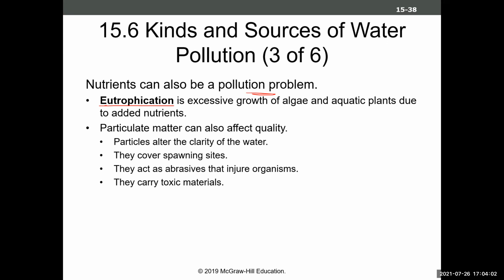And if you get enough organic matter to grow and fall to the bottom, all of a sudden you have a high BOD issue now. So that decomposition is going to happen, and you can end up with a dead zone because of eutrophication from water runoff. And this is actually a problem in the Mississippi Delta because the Mississippi drains the interior region of